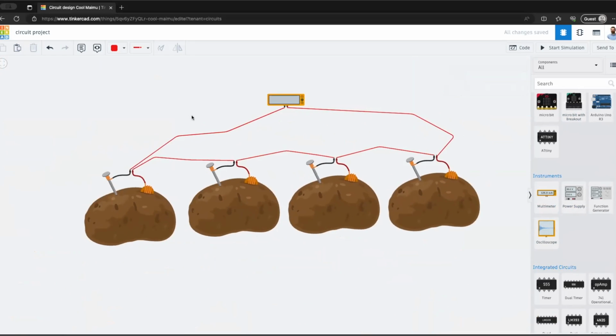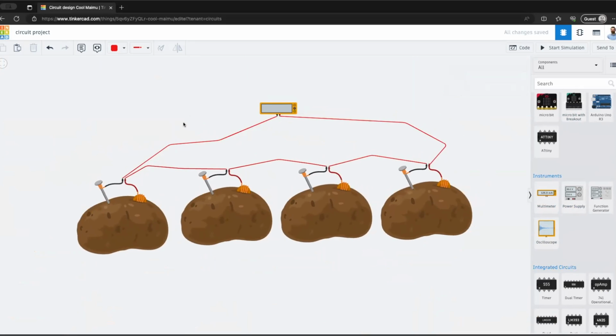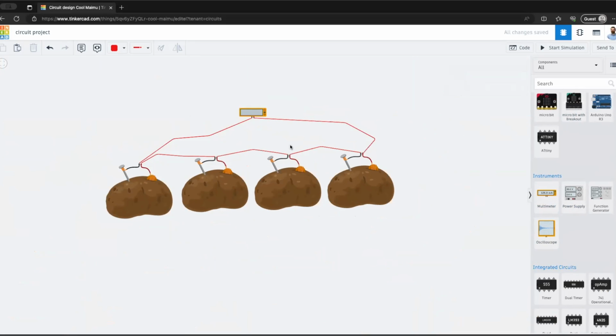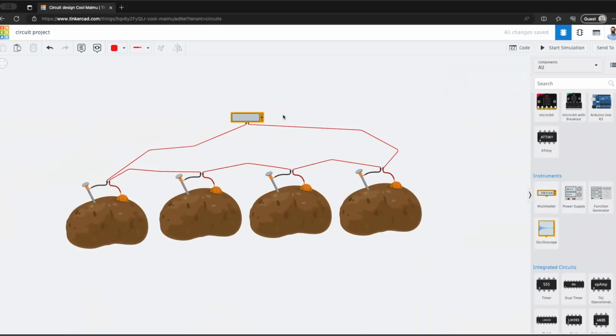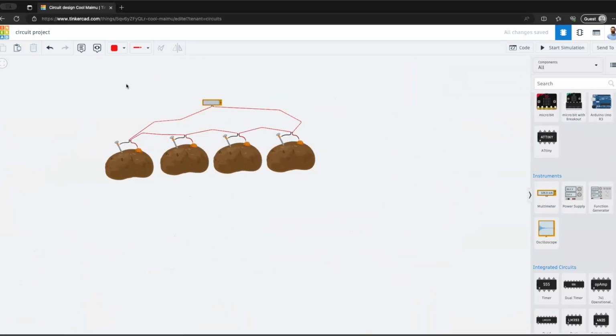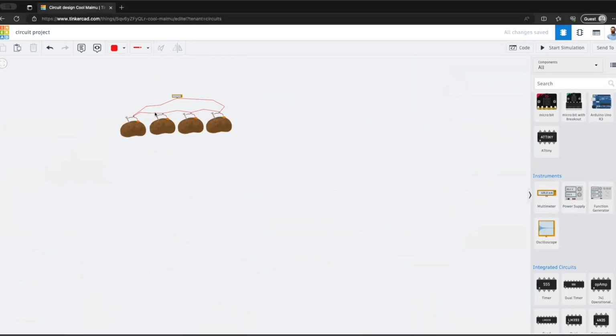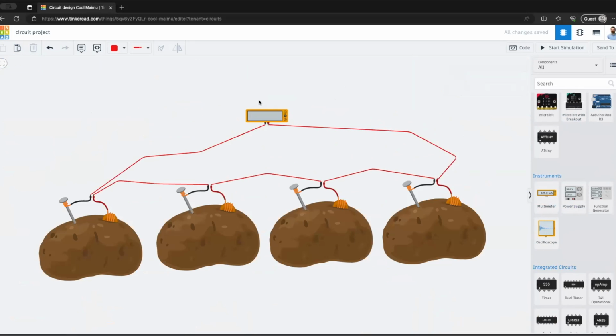All right, you'll notice that I keep zooming in and out in the workspace, so you can use the same kind of Tinkercad tools to zoom in and out with your mouse wheel and select things and pan around. And if you ever want to make your design fit, so if you get kind of lost like this because you have a really big design, this button right here in the top left corner, or F on your keyboard, will make your entire design fit.